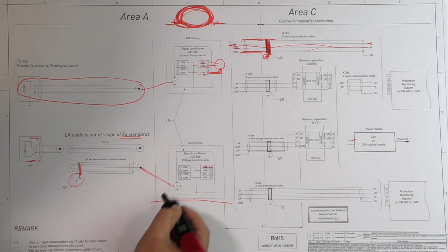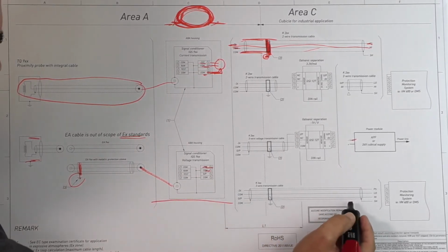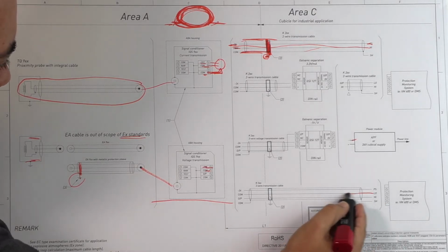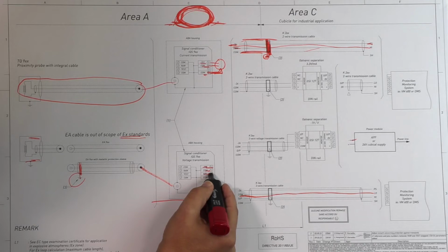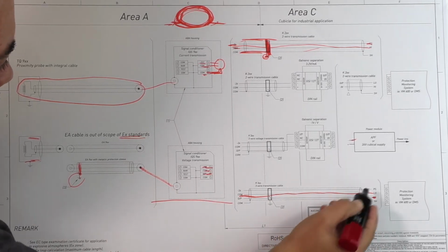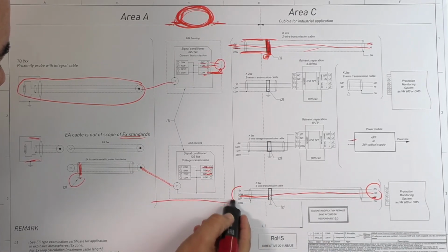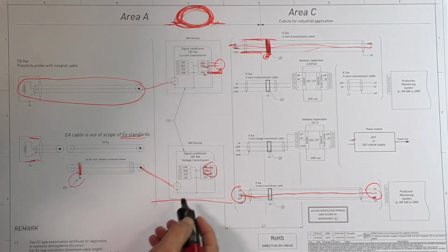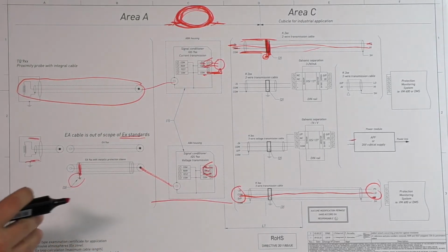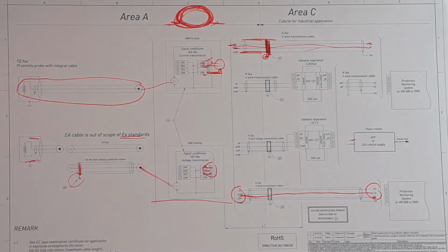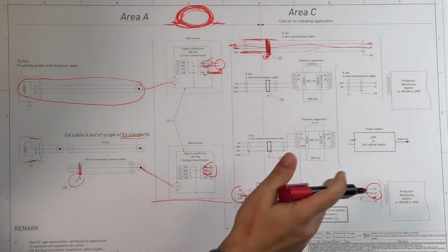Again, you have the minus 24 volts, the COM connected now to the low of your system, and the output will be connected to the high. And these three signals will be like these two, carrying your information, your electrical signal that will send the sensor information to your system.